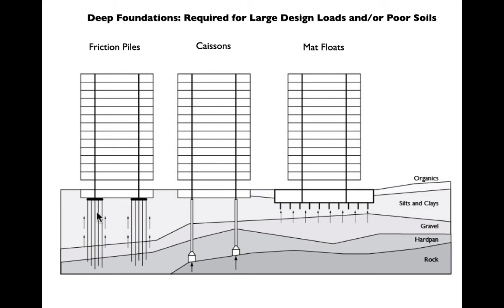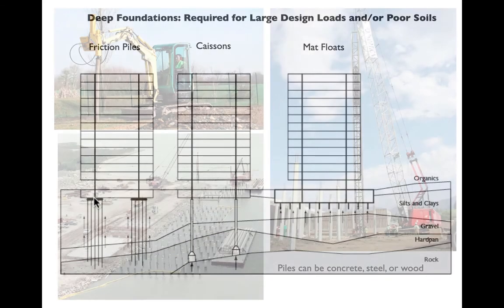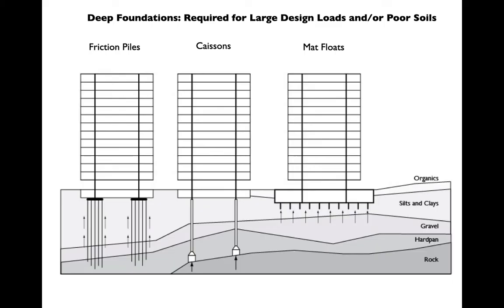And this is showing often very deep column caps because you do get big shear loads here, right? This ends up working like a distributed load, fairly discrete distributed load, but nevertheless, you can think of this as a distributed resistance. And here we have the point load, and you can imagine that that's going to give us a fair amount of shear.